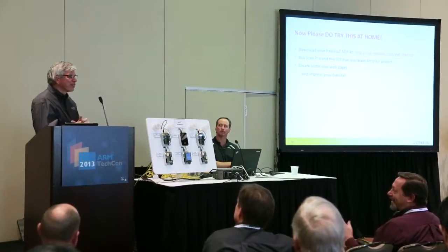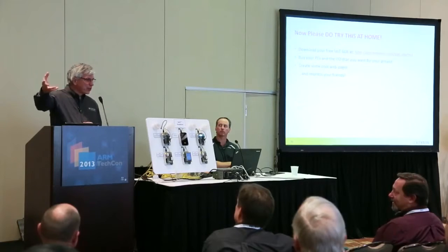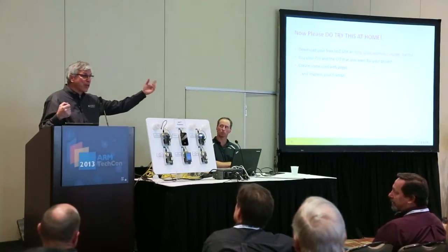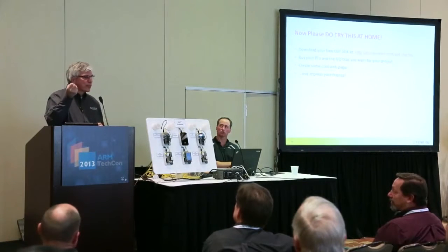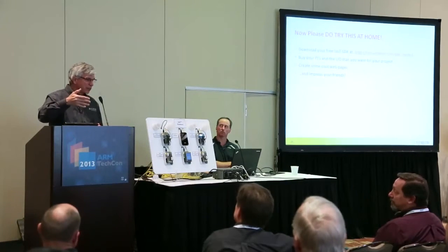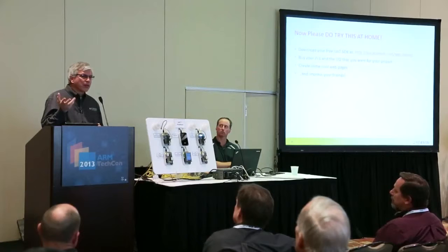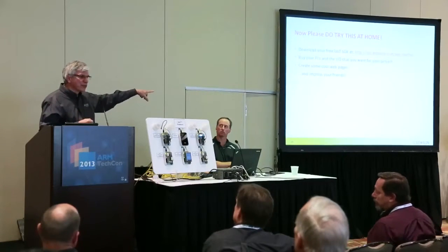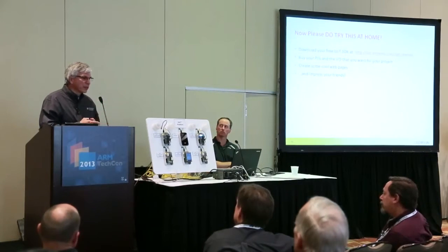Okay, yeah, I'll repeat the question in case you didn't hear it. So the question is, say I have some sensors that are communicating with some other devices, they're exchanging data, right? But I said that another sensor could come onto the network and it may pick a duplicate address, and the first one would change it. So the way that happens is there's another unique identifier created for a connection that truly is unique, kind of a globally unique identifier that's created for a connection that's managed by what we call a connection host. So when there's multiple devices connected, one of those devices is a connection host. In my diagram with the push buttons, it was that first one I pressed that became the connection host. So it created a globally unique identifier as well as the smaller identifier that's typically used.